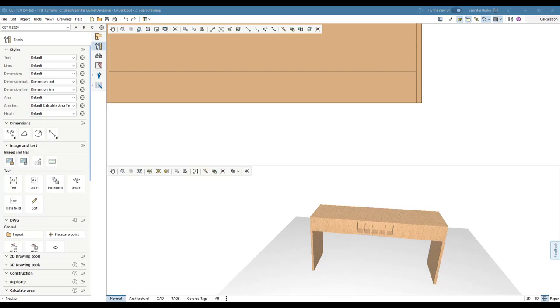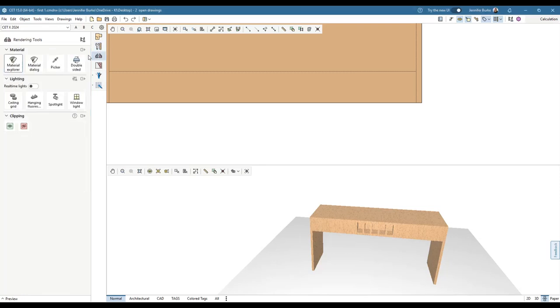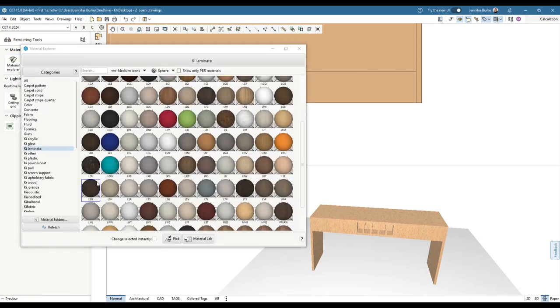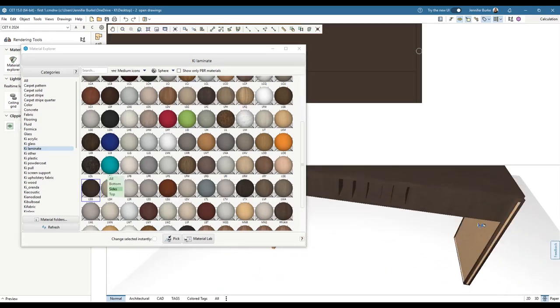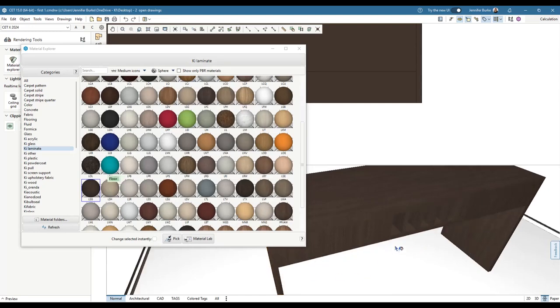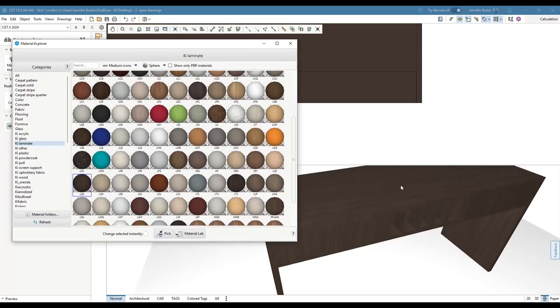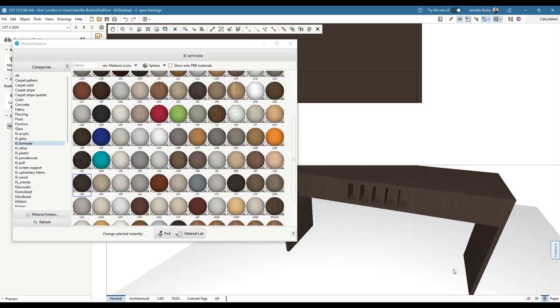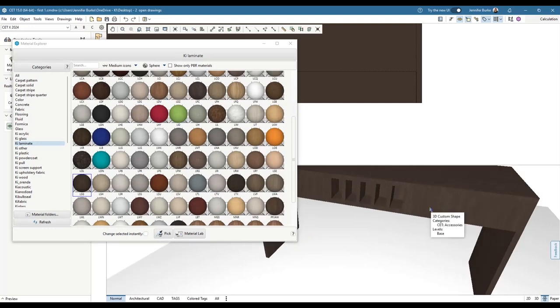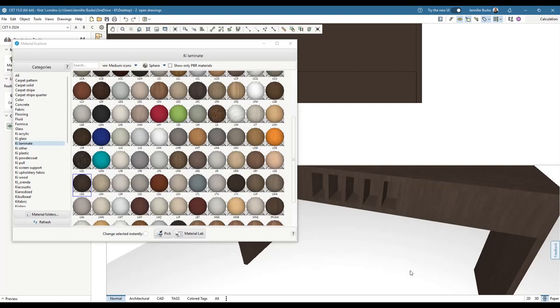To finish this one up, we'll talk about applying finishes. You can either create a finish or locate one in the Material Explorer and apply. So we'll get one of these applied to all of the faces, edges, the uprights, etc. And let's take a look at how the grain direction is going. So something to consider is ensuring that the grain direction is represented correctly going left to right, for example. So this front facade and these edges, in my history with furniture, I have seen it going left to right on the widest part of the laminate.